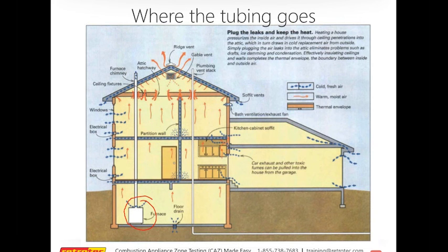And this again is a best practice. I'm going to take this basic picture here, and I'm going to say that here we have our combustion appliance zone. Okay? Now, as I mentioned, you want to set up the blower door. This was recommended to me by my guru, Keith Williams in Wisconsin, who said, if you're going to set up the blower door and the combustion test at the same time, then maybe you should set up the blower door closest to the combustion appliance zone. And that's a really good idea.